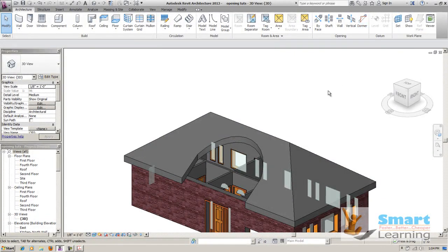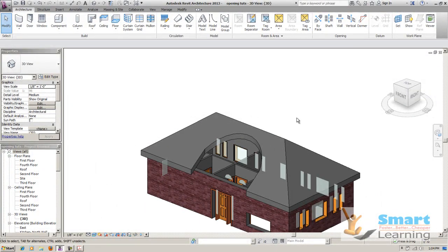Like this is the dormer one also. The dormer is also a creation which you can do inside the roof, that I will discuss in my coming session. So just practice all these 4 in brief by taking different conditions. By face, you can apply to the roof or the floors or the ceilings, anywhere you can have it. Shaft is very specific for large scale openings. Walls, you can select the walls and do the openings. Vertical you can use for the roofs and floors and ceilings everywhere. And finally the dormers I'll discuss in my coming session. Thank you.